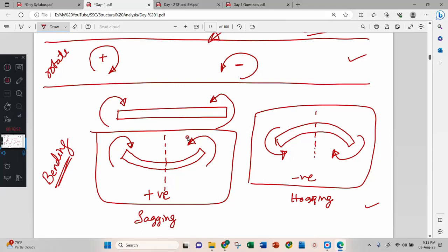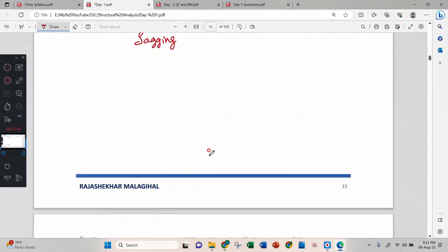That's why whenever you determine bending moment, you should not say clockwise, anti-clockwise. When you calculate bending moment, clockwise, anti-clockwise, no, you should not pronounce like that. Bending moment means sagging, hogging. Okay? Then only moment means that is clockwise, anti-clockwise. This is our sign conventions we will be using.